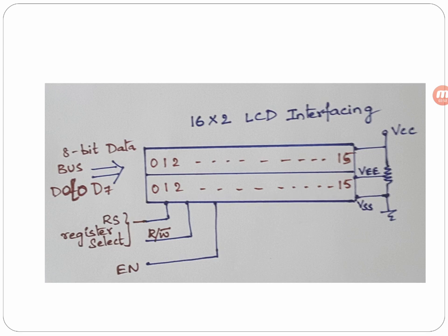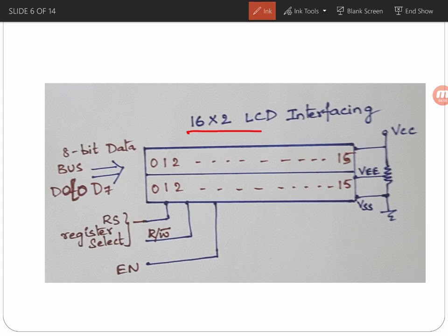And then going with the basics, studying the LCD signals. As you can see in the picture, it is a 16 by 2 LCD. First what is required is the data lines D0 to D7. Whenever the microcontroller wants to display something, give a command to the LCD, or read the status of the LCD, it is done using the D0 to D7 lines. And then we have a few control signals.